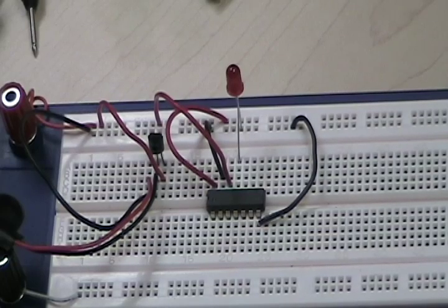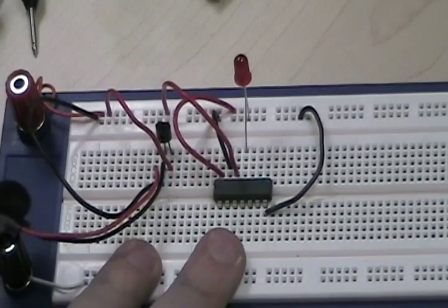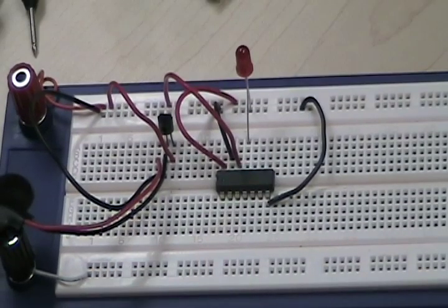Okay guys, this is a NAND gate. So remember, the output of an AND gate will only go high when both of its inputs are held high. Oppositely, if we turn on the power and put both of the inputs high, then the output will go low. Otherwise, no matter what, the output will stay high. Now remember, if you need to go back, or simply Google NAND gate or AND gate, you'll get a truth table of it. But try to remember it, because it's not hard to memorize.